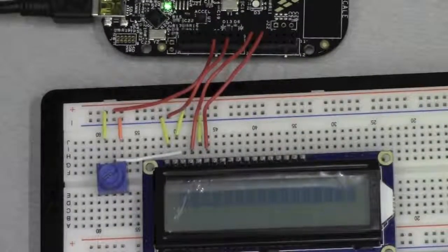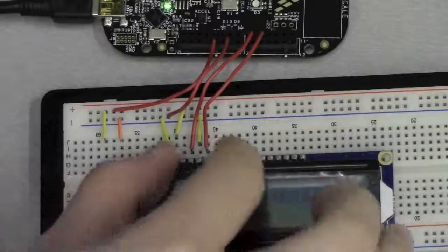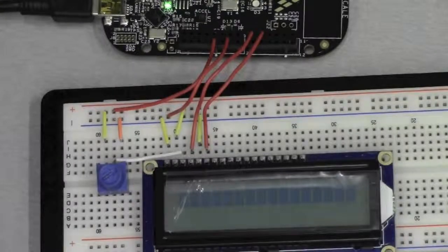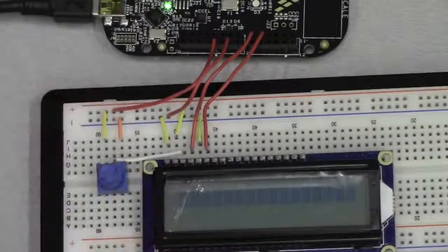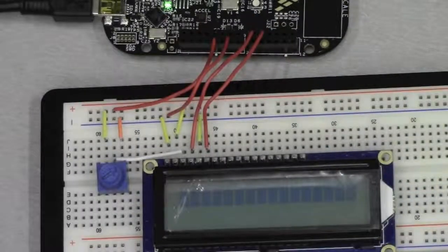Down from there we have digital pins 0, 1, 2, 3, which we don't want to use. So pins 7, 8, 9, 10 are going to be completely empty. Then we're going to start from digital pin 4, 5, 6, 7, which is going to be connected to any sort of random digital pin on the microcontroller. Again, we're going to be using the top remaining 4 on this KL25Z to operate it.